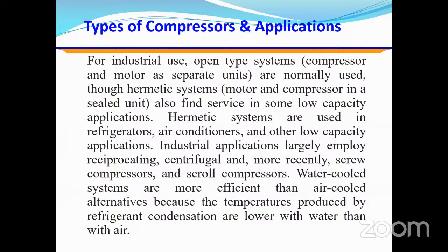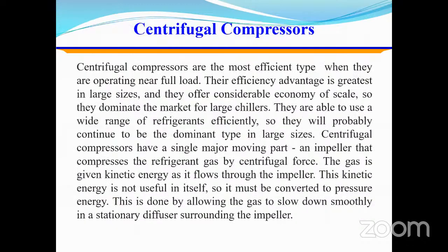Water-cooled systems are more efficient than the air-cooled alternatives because the temperatures produced by the refrigerant condensation are lower with water than with air. Centrifugal compressors. Centrifugal compressors are the most efficient type when they are operating near full load.